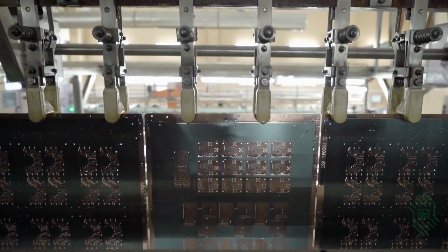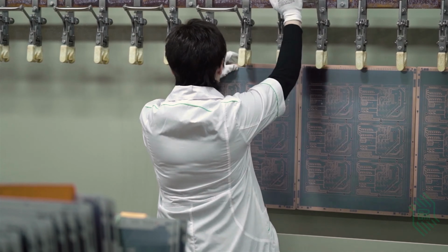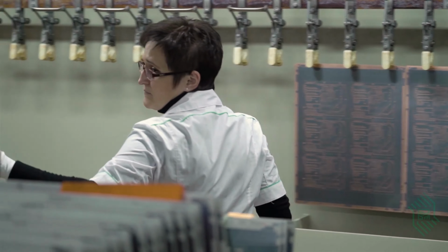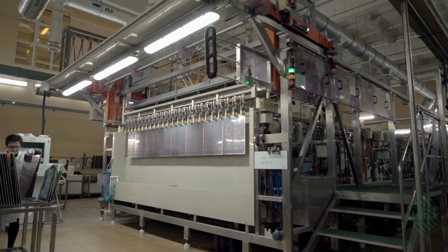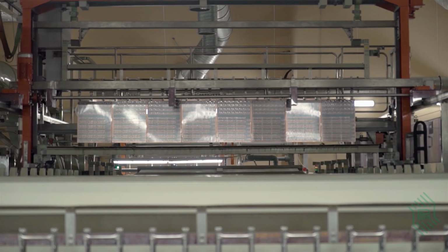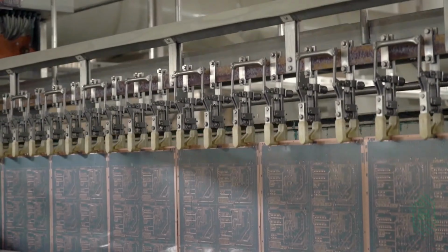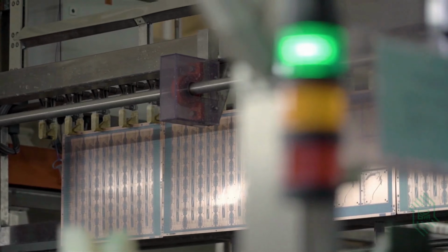The pattern plating produces a metal layer of the required thickness in the PCB's holes. The auto operator takes a jig with the panels and moves it sequentially through all the necessary preparatory steps, including surface cleaning, micro-etching, and pickling. Further, the fly bars with the panels are plunged into the copper plating bath for 60 minutes.